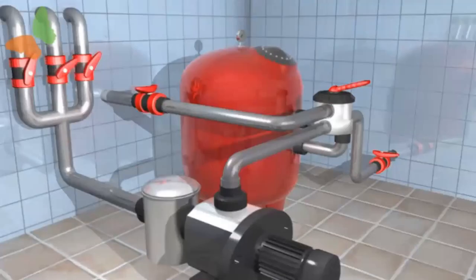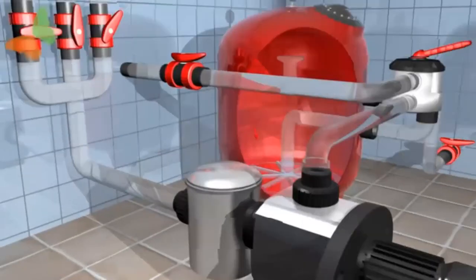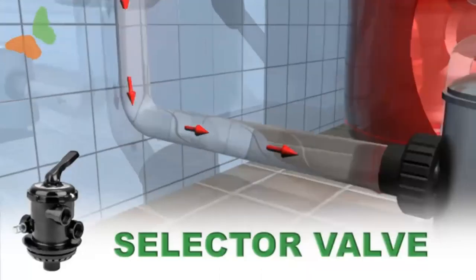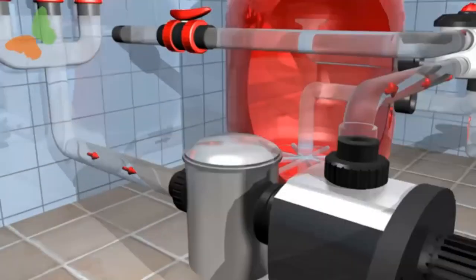The water coming from the skimmer and the drain is regulated by the valves and pushed by the pump to the top part of our filter. The pumped water passes through the selector valve, which, depending on its position, allows us to choose the filter function. Inside the main filter, there is a filter bed made of sand or glass grains that retains the smaller particles that come from the pool.